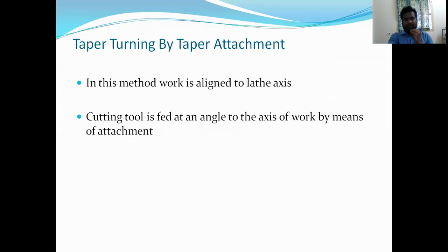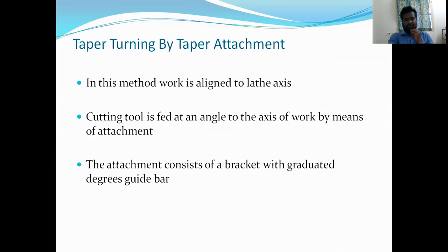In this method, the workpiece is aligned to the lathe axis and the cutting tool is fed at an angle to the axis of work by means of an attachment. The attachment consists of a bracket with a graduated degrees guide bar.